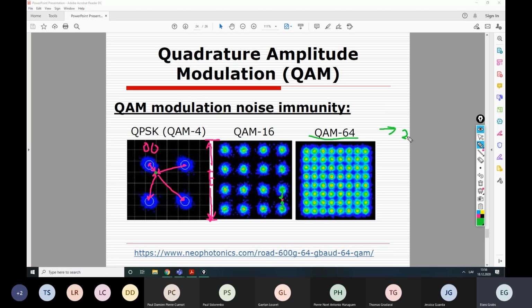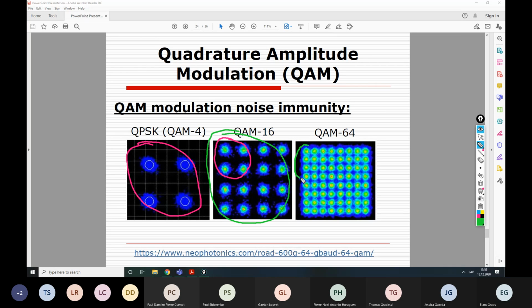And then follows QAM 256, which is actually even more densely compressed. So basically, as you can see here, this is here, right? This is just here. And the entire picture would be condensed into this region for QAM 256. And that would make it literally impossible to receive data correctly any longer. In this case, we already have many errors, right? So as you imagine, it becomes more and more problematic to receive data correctly.